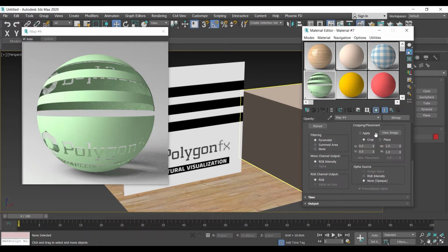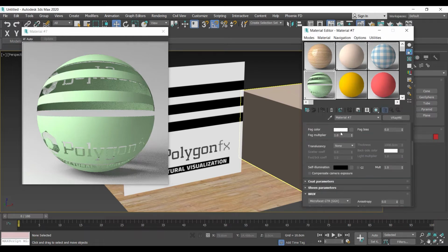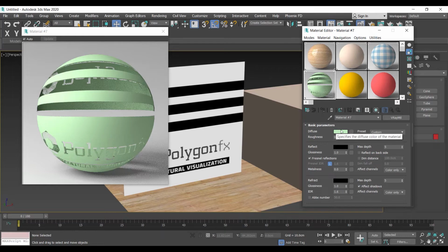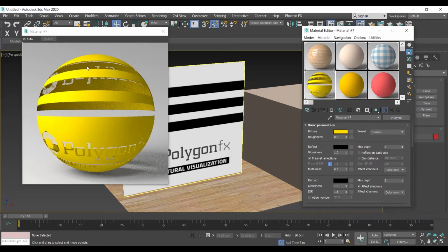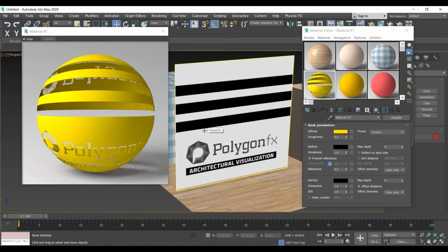to be taking the same material as the diffuse color that I put in here. If I change this color, for example, I make it maybe more greenish or yellowish or whatever color, you can see in here that it's yellow now, but it's cut where I have this kind of texture. Great. So this is perfect if I want to have some kind of transparency, and not the whole object to be transparent, but some part of the object to be transparent.